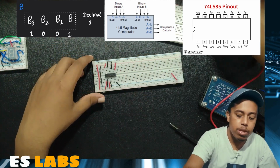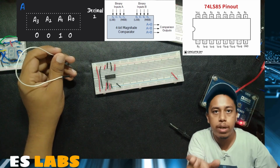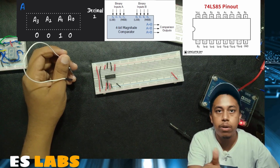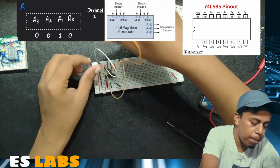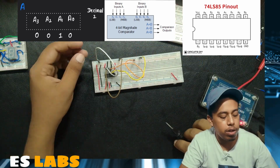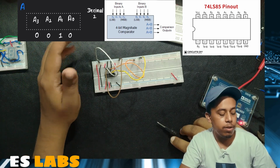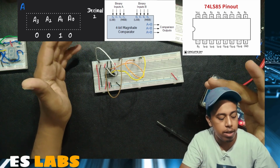Now we simply give the input to A. First we are going to give an input equal to 2. For that we connect A3 to 0, A2 to 0, A1 to 1 and A0 to 0. So now I have given the input through A also. A3 is 0, A2 is 0, A1 is 1 and A0 is 0. So A is equal to 2 and B is equal to 9. This represents that A is less than B.